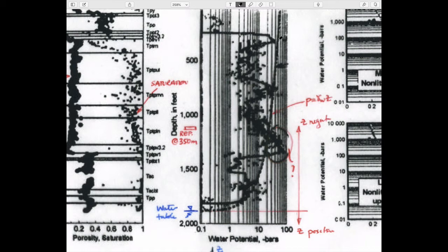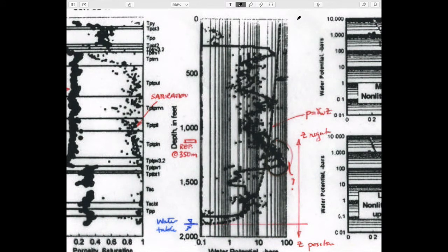Physically, what this means is if you went up to the surface here, and you took a column of water which was 600 meters tall, and you tried to hold on to it as it goes down into the ground 600 meters, and instead of pulling up on it, you applied a suction pressure so you could actually hold it there, the suction you'd have to apply would be this pressure here. Roughly, what is it, 50 bars? I'm not sure. You can calculate it out, right?